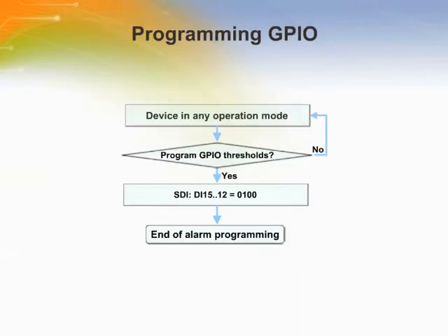The device has 4 general-purpose input and output GPIO pins. Each of the 4 pins can be independently programmed as general-purpose output, GPO, or general-purpose input, GPI. It is also possible to use the GPIOs for some pre-assigned functions.